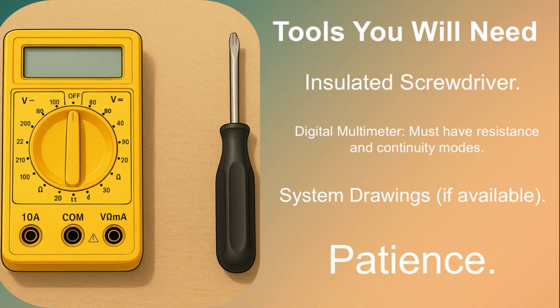To fix this, you need the right tools. You need a digital multimeter that has both resistance and continuity modes. You also need an insulated screwdriver for safety. If you have the system drawings, get them now, as they will help you locate devices. And finally, you need patience.